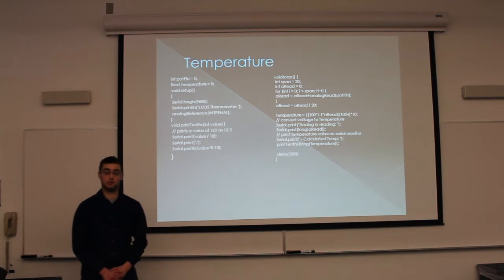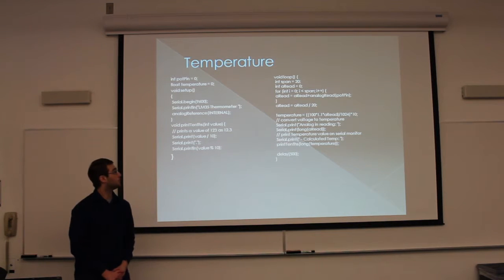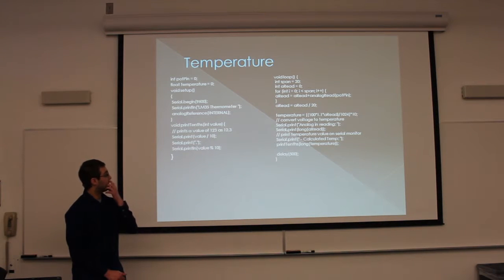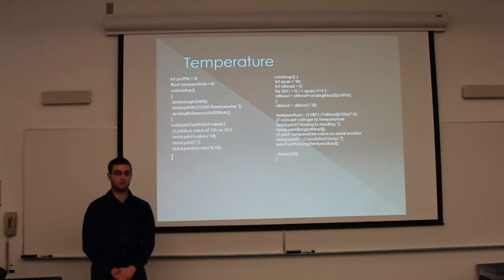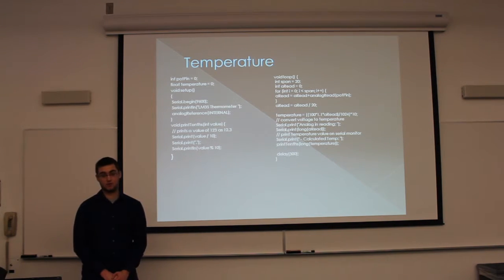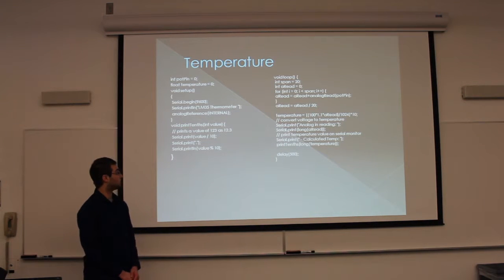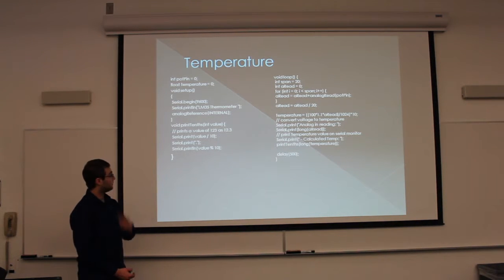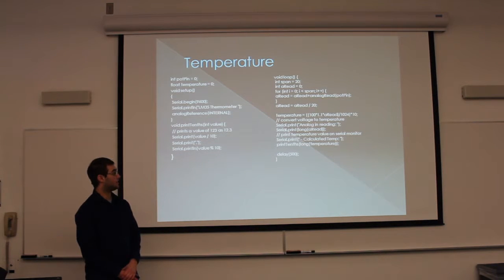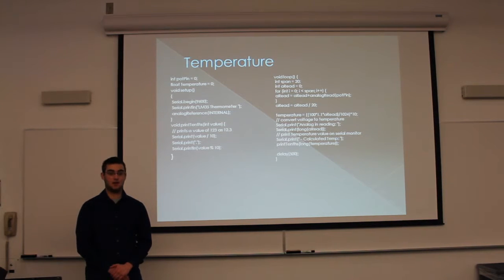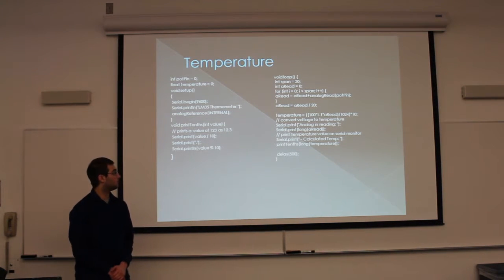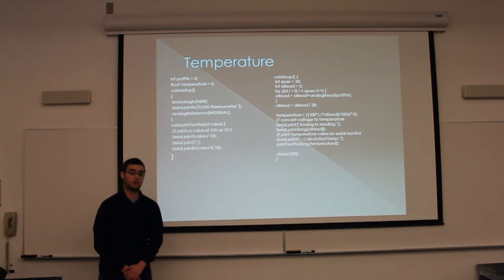in the serial monitor. So then if we go over to the loop, what this does is it analog reads the temperature of the transistor, and it performs conversions. If you look over there, temperature equals 100 times 1.1 times A read divided by 1024 times 10. That's obviously a lot of stuff that doesn't really make sense, but as it says below, it's converting the voltage to a temperature.